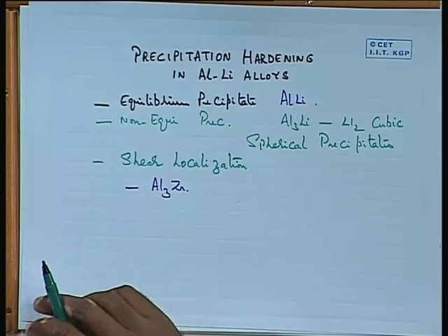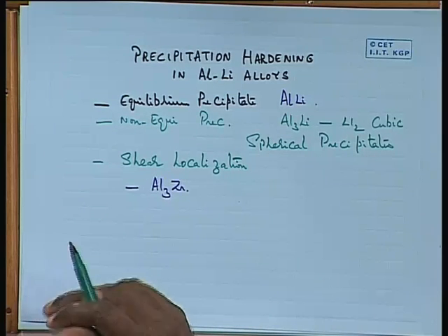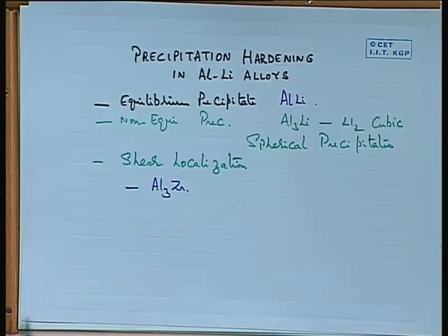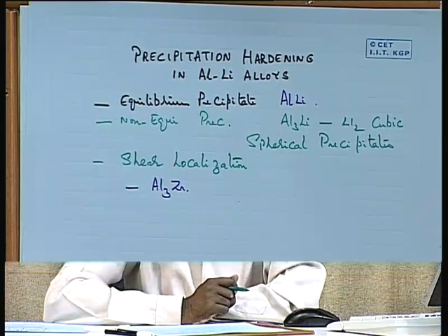Aluminum copper alloys, what is the maximum we go? 4.5. Why can't you go beyond that? So we come to the eutectic? Did you extend the solvus? No. The solvus line is near the solidus, there is a melting.